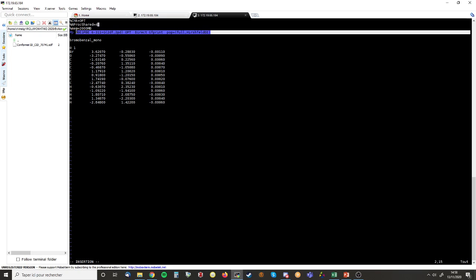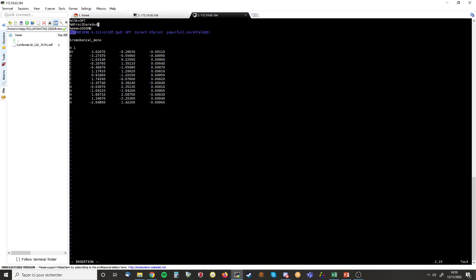So this line with the hashtag p is a line of computational method, and you must give it the memory size, the RAM memory that it can use. So it will use 2 gigabytes of memory. It will use 4 processors. Depending on your computer, on how many processors you have, I've chosen 4 so that I can launch quite a lot of calculations.